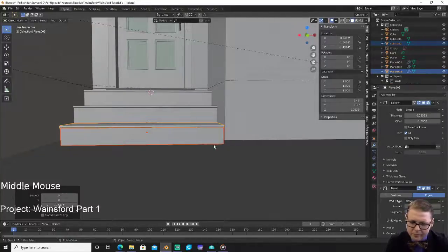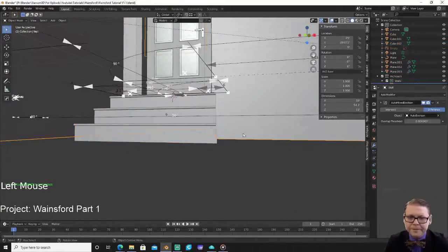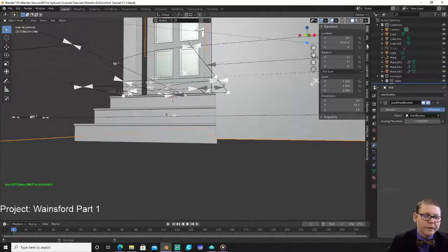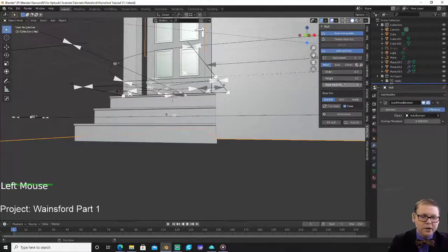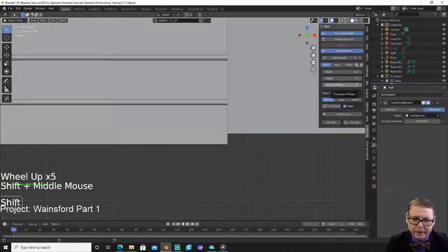Our bottom step is going to be a little bit shorter because, you know, this is the ground right here. But I suppose what we can do is just drop down our foundation a little bit more. Let's see. So if we go into Archipack and then our floor thickness, again, we'll just go ahead and eyeball it.